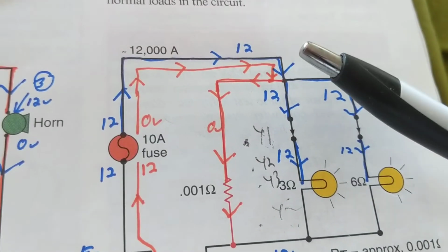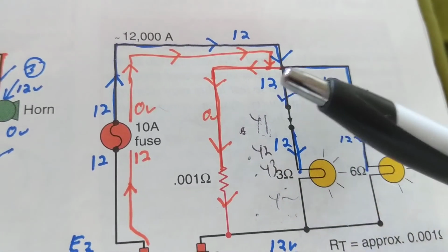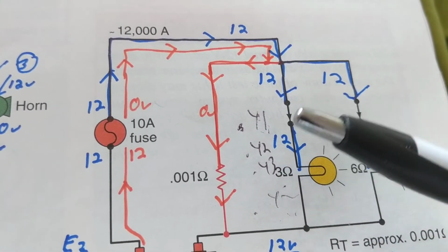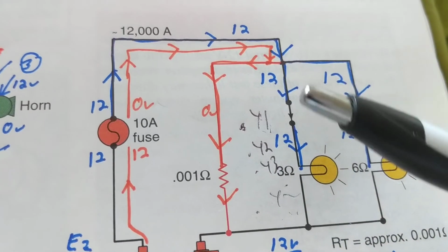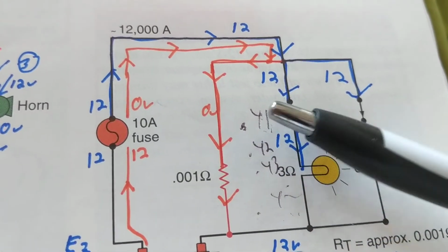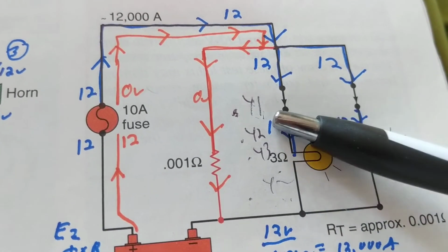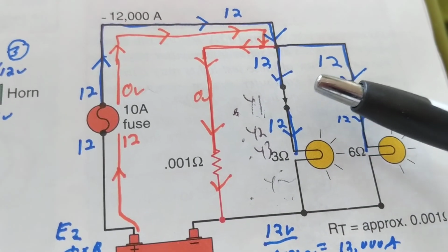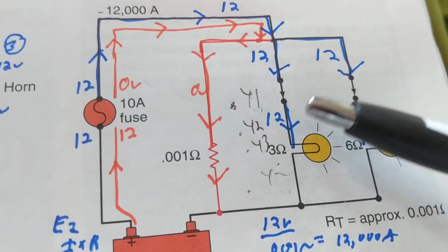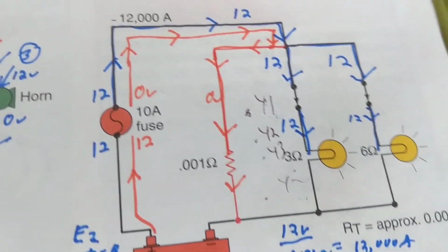And about the TPS sensor, again, you have to adjust it correctly. The PCM, or the ECM, looks at every single numeral. Like I said, 0.5, 0.51, 4.5, 4.6, 4.7, 4.8 makes a difference.